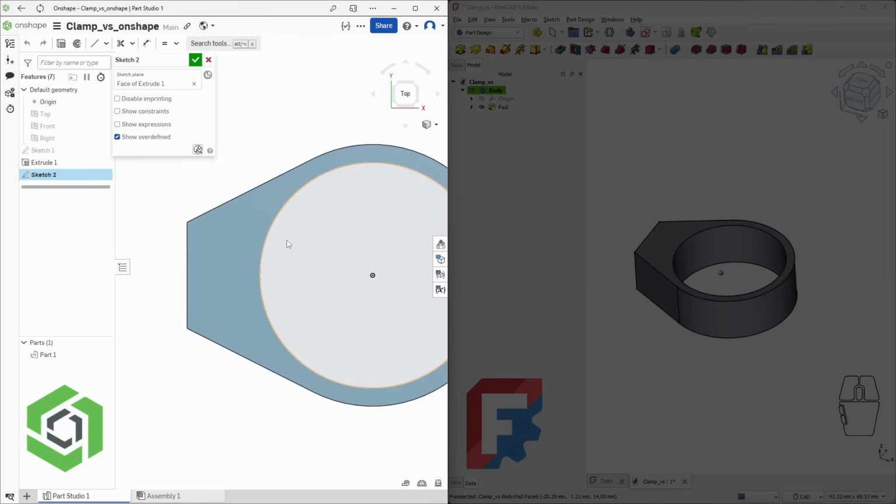We will start by drawing a center line that will serve as the axis of symmetry. Click on the Line tool, then draw a horizontal line starting from the origin and extending to the midpoint of the left edge. You will notice that Onshape automatically offers to snap to the edge. Press Escape to stop using the tool.